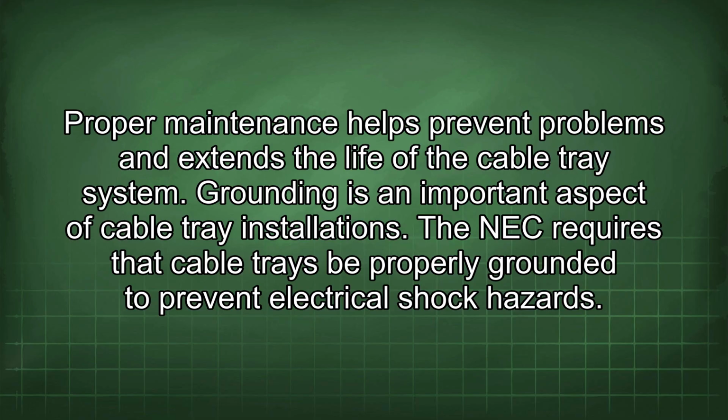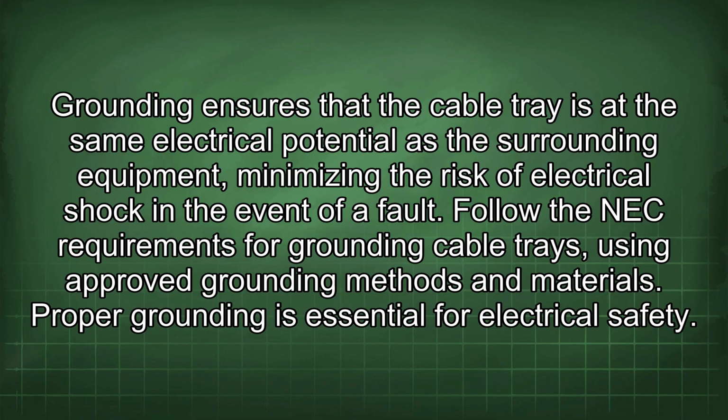Grounding is an important aspect of cable tray installations. The NEC requires that cable trays be properly grounded to prevent electrical shock hazards. Grounding ensures that the cable tray is at the same electrical potential as the surrounding equipment, minimizing the risk of electrical shock in the event of a fault.